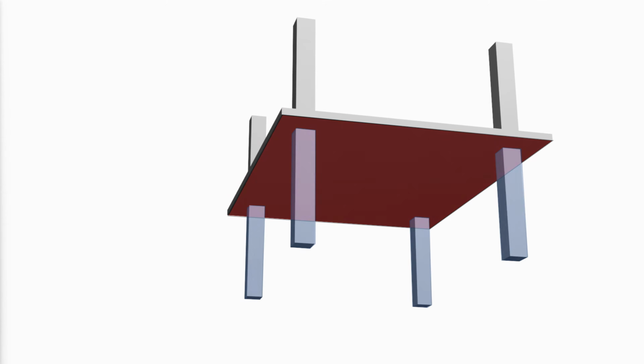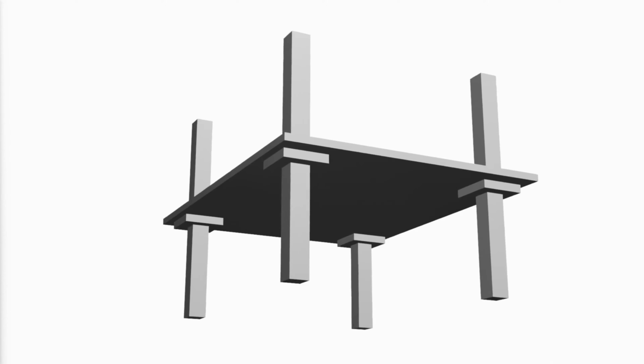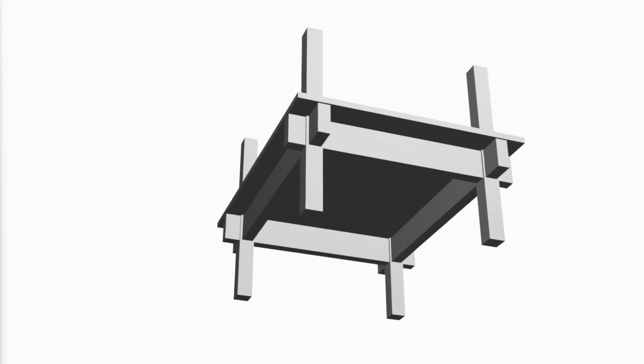Flat slabs are two-way concrete slabs supported directly on columns where the slab is thickened around the columns. Those thickened portions are called drop panels. Two-way beam-supported slabs are two-way concrete slabs with column-line beams on all four sides of a panel.